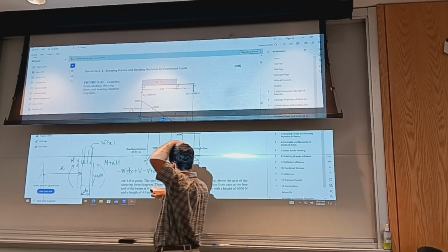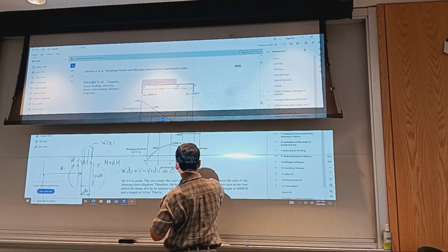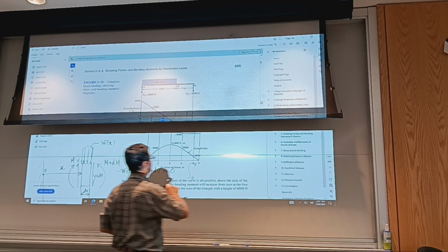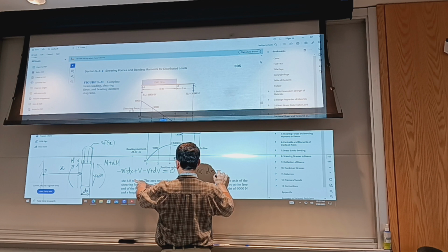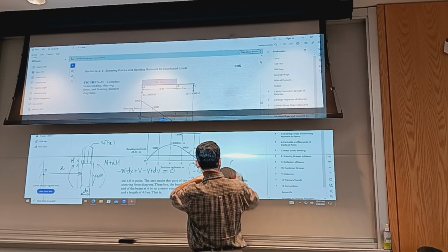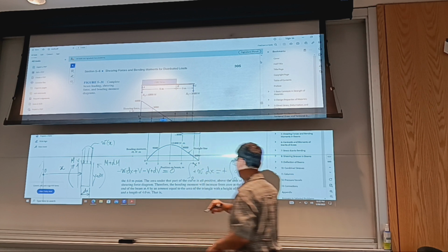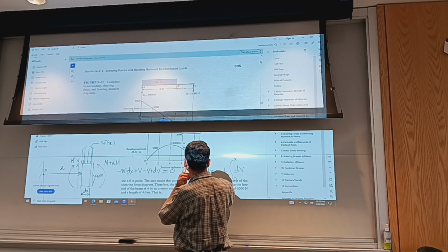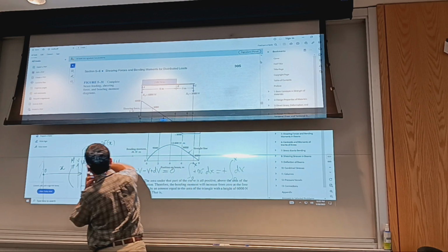Okay, so I'm interested in V, and V goes out. I have dV. So go on and integrate, integral from 0 to the current x of negative w dx equals, it will go negative, from 0 to x of dV. All right, so I can change this to positive. Okay, and then doing this, it can be a constant value in case it pulls in front, but it can have another shape, could be a parabola.